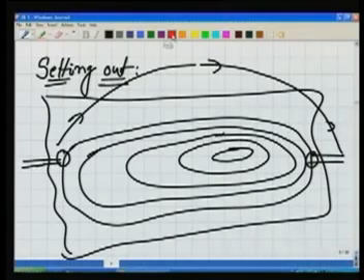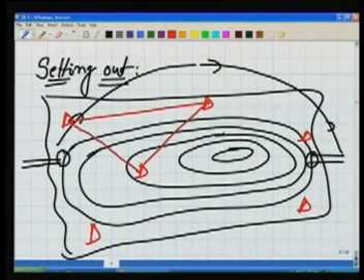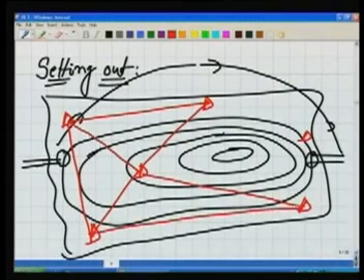In the previous figure, we have, for example, let us say established a triangulation network. These points are intervisible, and in order to map this area, a triangulation was done. So this is a network of triangles using which the area has been mapped.